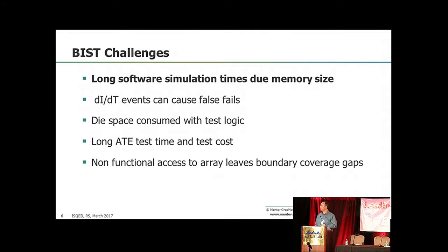So some challenges with BIST. BIST patterns take a very long time to simulate. Most of the time is spent waiting for the memories to evaluate, to go through all the March algorithm things like that. These things can take months to simulate in software.